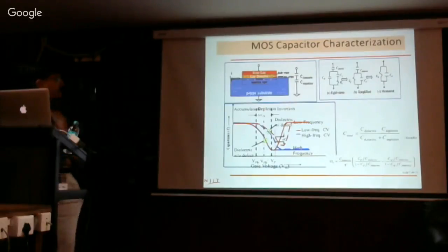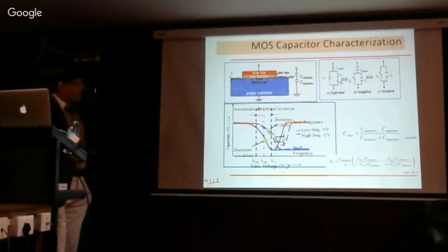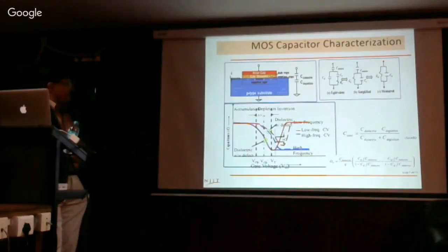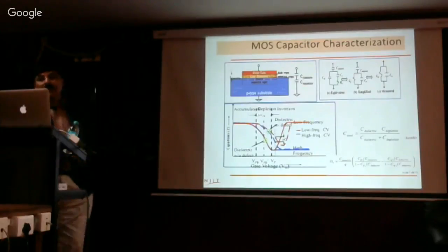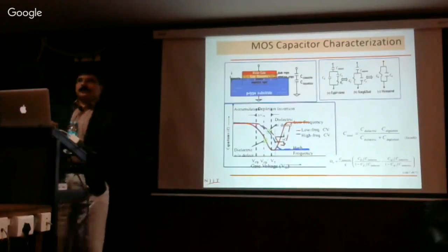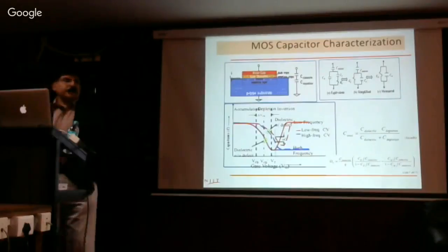And then you calculate the total capacitance that way. And then the interface state density, you calculate also from the low frequency measurement and high frequency measurement and the total dielectric capacitance. From this measurement, you can actually estimate the interface state density.